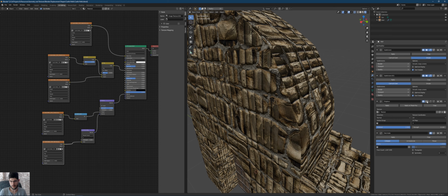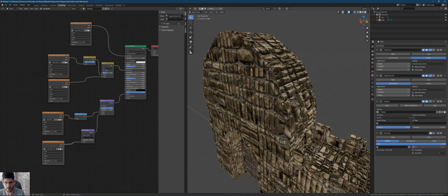Okay, and now we basically activate the displace option again, which, because we have a lot more polygons to work with, should, in theory, make it look a lot better. So we could probably push that strength a bit higher. And the decimate option, we're obviously going to go from a ratio of 1 to 0.05. And so we're going to get rid of most of these polygons. We're probably going to end up having a mesh with 2 million or something like that.